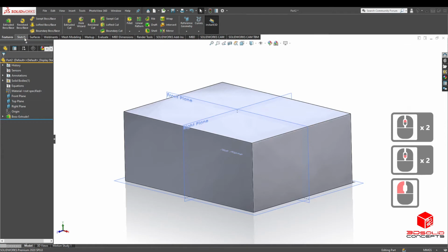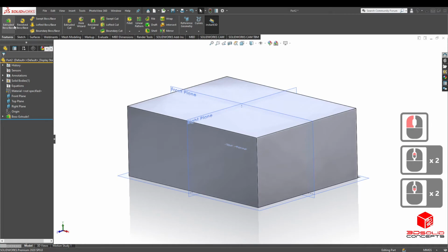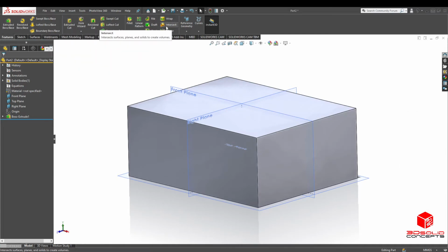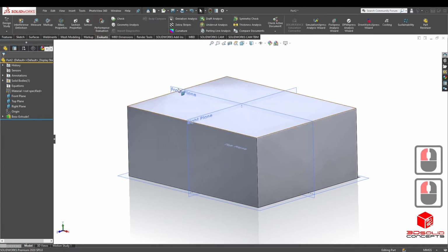Now let's get to know what SolidWorks is about. If you've noticed, we actually use this sketch for any 2D items. So all of our 2D commands will be housed in this sketch panel. We'll go more in depth on what each one does as we go through the tutorials. In the features panel, these are the tools that actually manipulate or create 3D geometry. So we'll only be really using features, sketch, and evaluate. We will be using much more later.